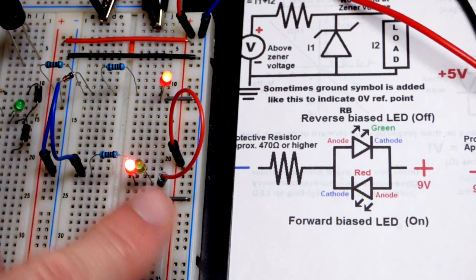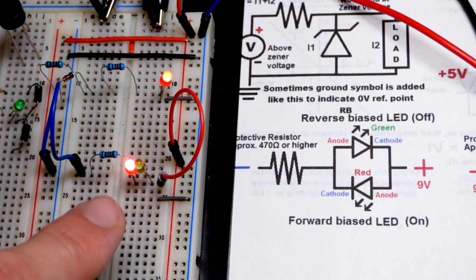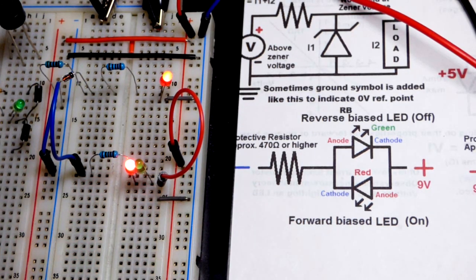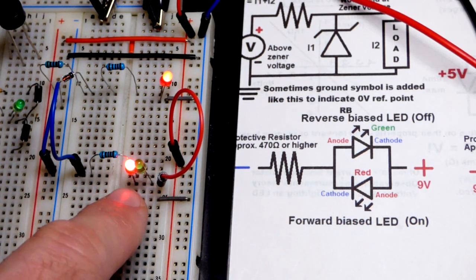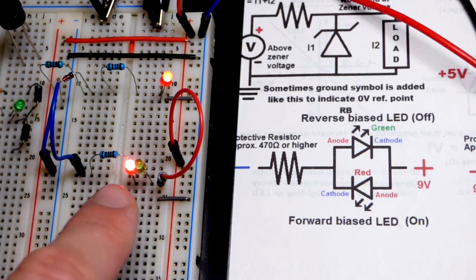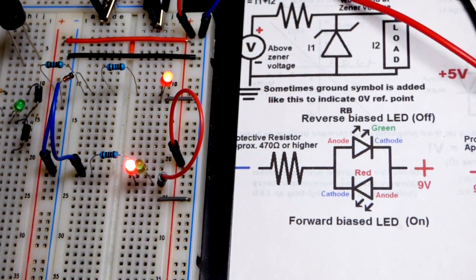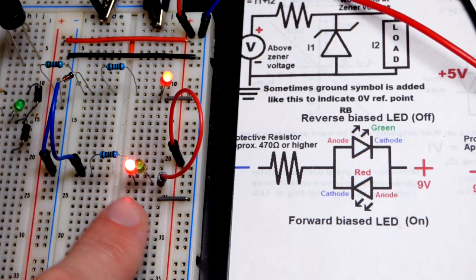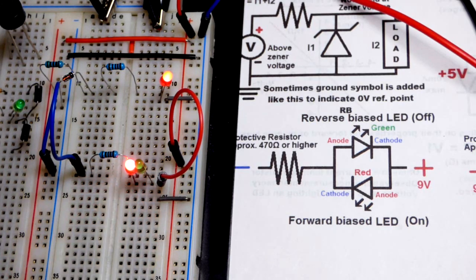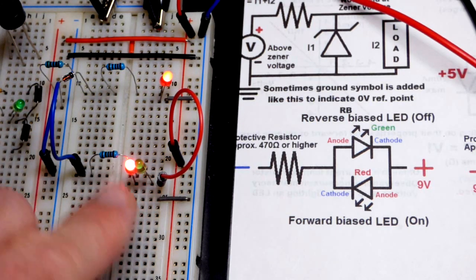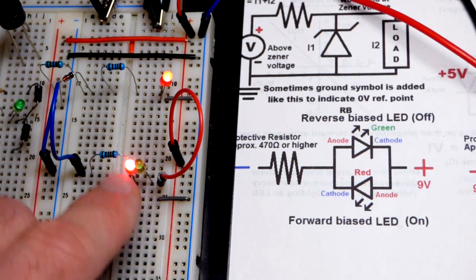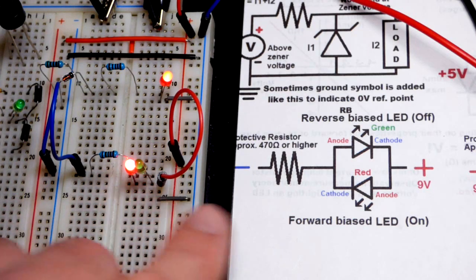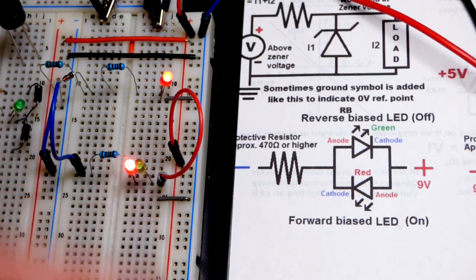So as long as you know what the color means when it comes to the direction of current, you can tell. Now, if both of these look like they're on, and you know you wired them in opposite directions, it's impossible for them to be on at the same time, but they can look on if they're flashing back and forth fast enough. That's really easy to do. If you change the direction like 15 times a second or something, they start looking like they are both on completely. They won't be as bright, but in any case, if you know you wired it properly and they both look like they're on, that means the polarity is changing very rapidly.